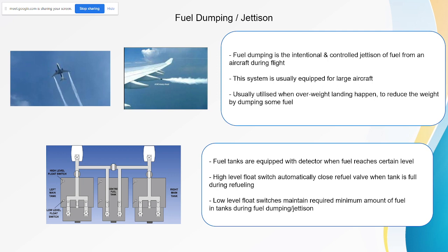Okay, sir. So I have a question, sir. Go ahead. How about if the aircraft wants to do ditching in the ocean? Does the aircraft need to dump the fuel also? If you ditch into the water, why do you need to dump? It's an emergency already. Unless you want to land at the airport, that means you have to comply with the landing weight of the aircraft to minimize the damage to the aircraft.